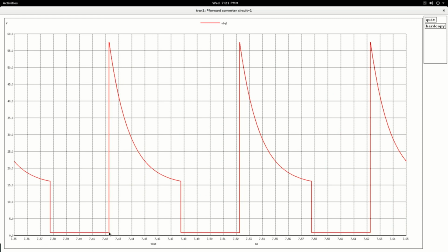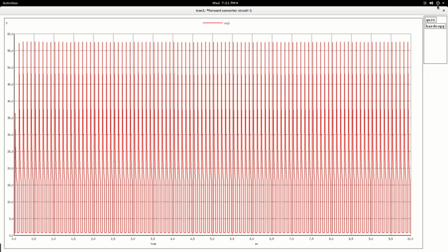This is the on time, so therefore the on state. Then the moment the BJT switches off, you see a high spike, and then the voltage decays exponentially and goes towards the Vin value or VCC value. So this is typical of the lossy flux reset, and this exponential decay is the Lm by R time constant, and this is due to the decay in the magnetizing current. So this is one important waveform which I wanted to show you.